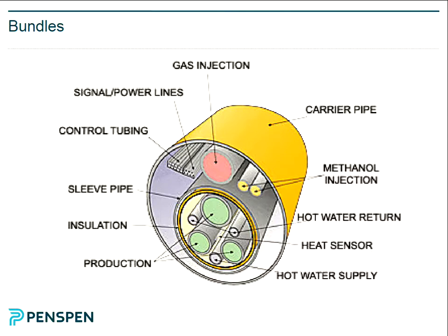Typically a bundle is flooded full of water, but it's inert water. It's been treated, so it has corrosion inhibitor and oxygen scavenger in it. It's a completely inert environment. It's sealed, so there's no transfer of fluids. So corrosion's not really been a problem.